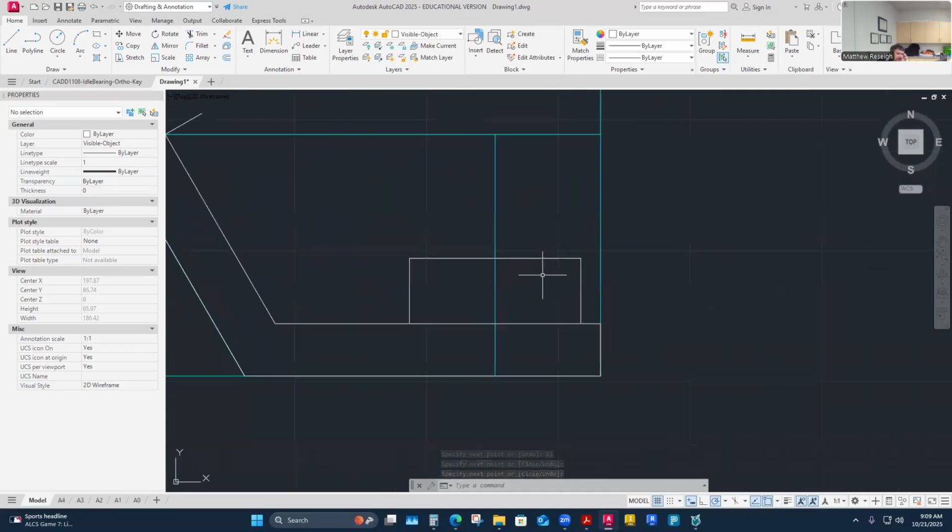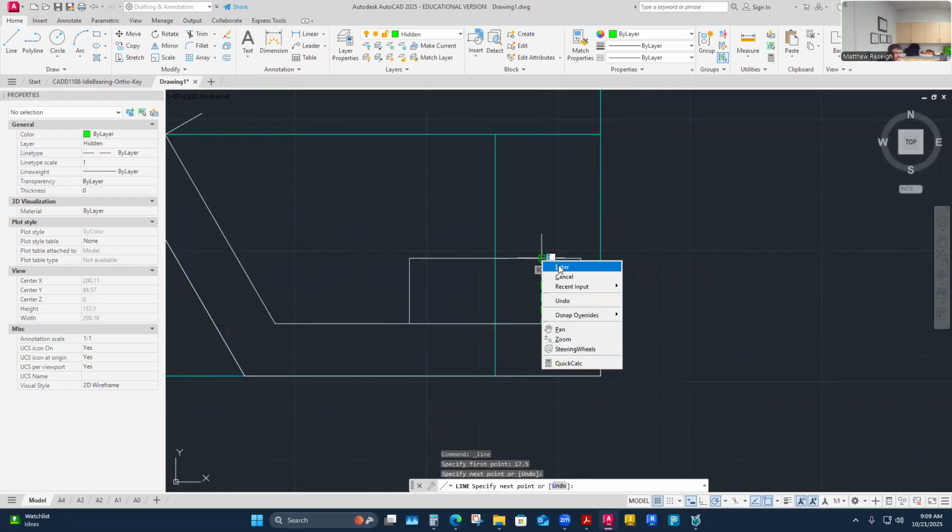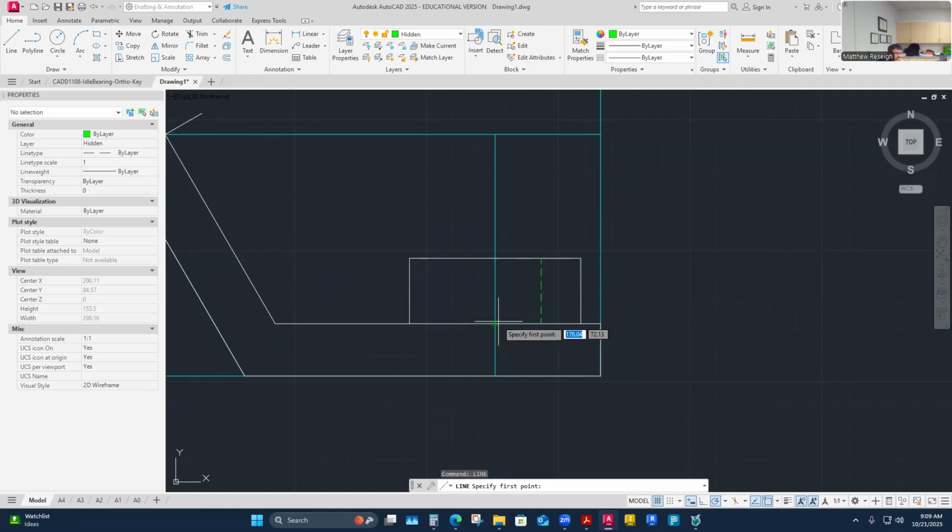And then it has an inner bore that will be hidden, and I can put that in here while I'm here. Maybe I'll just put it in as hidden line work just while I'm thinking about it. It's going to look like, what, 35? Half of 35 is 17 and a half. Pull out your calculator if you need it though. I say 17 and a half. And this will be the through bore here. So I might repeat that over here. I could mirror that, but I can just probably enter in 17 and a half. So that's that inner bore.